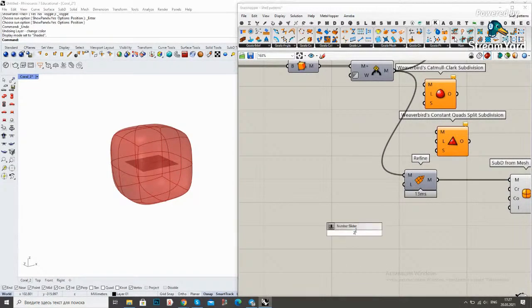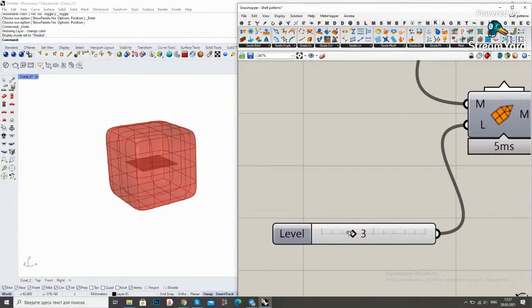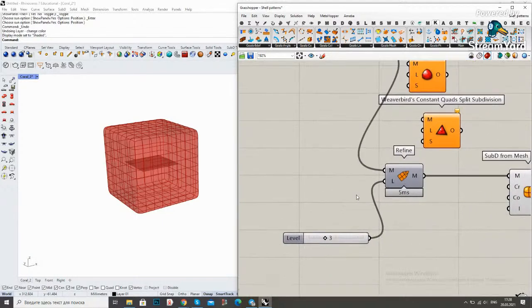If we increase the level of subdivision, and here by subdivision, I know it's a bit confusing, but I mean the more traditional understanding of this notion, which is basically dividing a face, using a kind of fractal-based algorithm, into 4 faces, or 16 as now, or 64, and so on. And you see that with each subdivision, the shape becomes more and more rigid, closer and closer to the initial geometry, right?